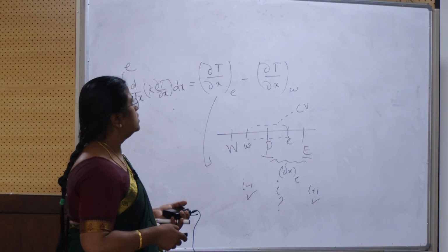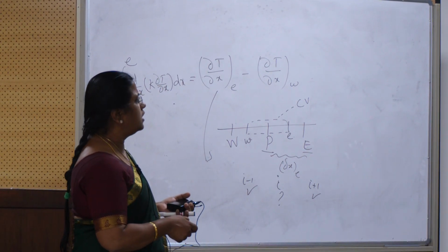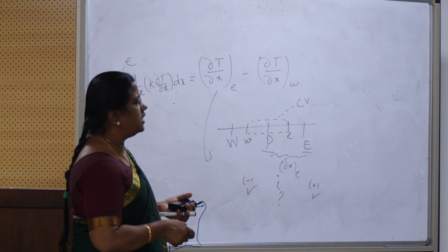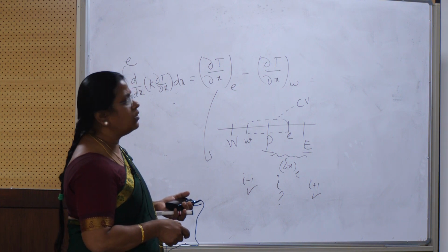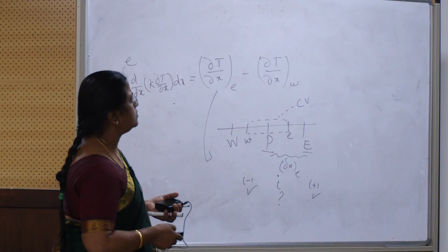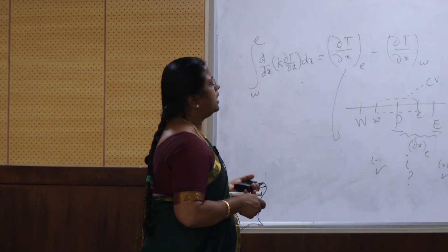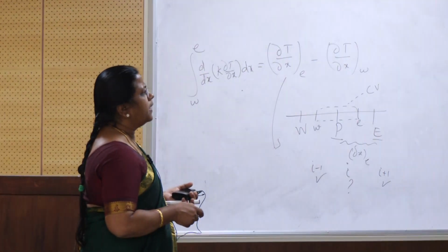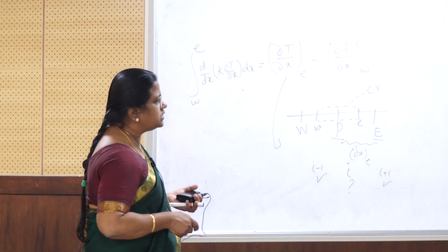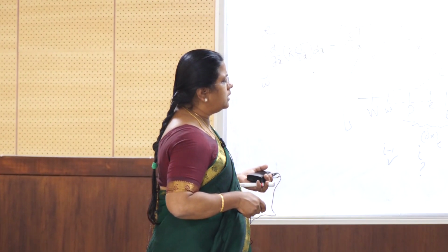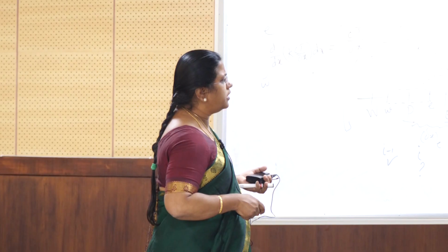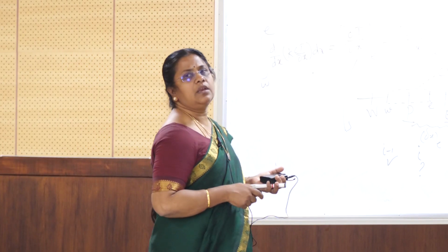Then let us understand a little bit about this source term linearization. In which way do we have to consider this? If I have S bar in this form, then I can rewrite it such that it is written in this form, with this coefficient less than 0. We are rearranging only, it will not come automatically.